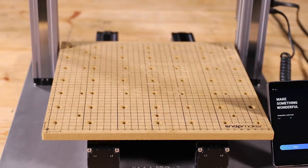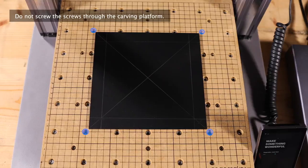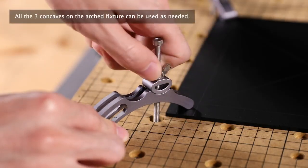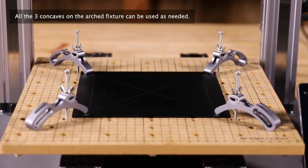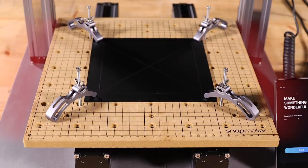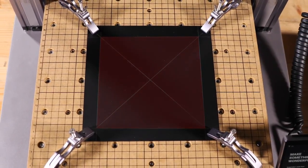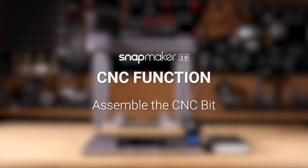Fourth, position the clamps. Place the material at the center of the platform and choose the proper screw holes to fix the clamp sets. Fifth, fix the material. Firmly put the thinner side of the arch fixture onto the material and fasten the wing nut. Follow this step to fix the left clamp sets. But to avoid collision, it's important to prevent the clamp sets from extending out of the platform or overlapping the largest possible carving area.